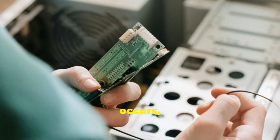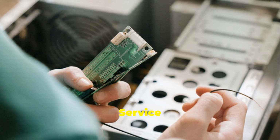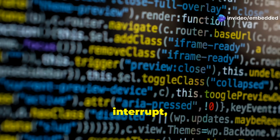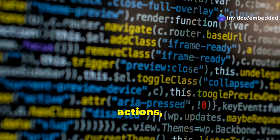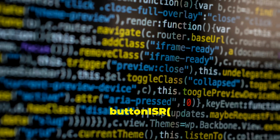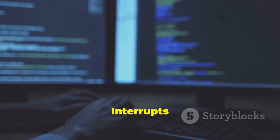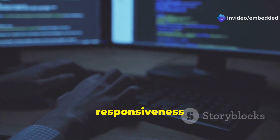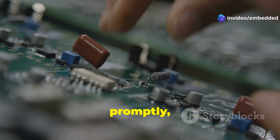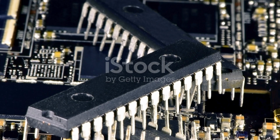When an interrupt occurs, the microcontroller jumps to a special function called an interrupt service routine, ISR. The ISR handles the interrupt, performs any necessary actions, and then returns control back to the main program. Void buttonISR, handle button press. Interrupts are vital for real-time responsiveness in embedded systems. They ensure that critical events are handled promptly, even if the microcontroller is busy with other tasks.